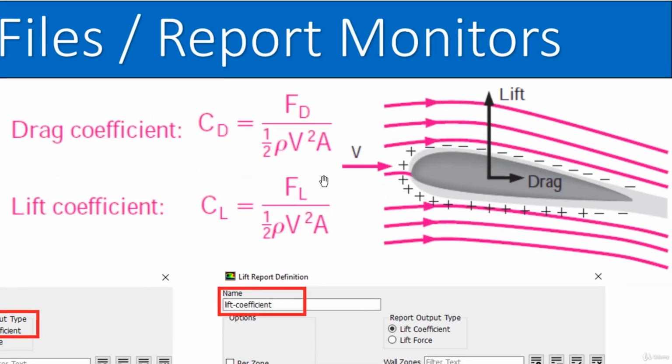To define the x and y components for the drag and for the lift, I want to show you how you can understand which component should go where. Flow is coming at a zero angle of attack, that is, the angle between the chord line and the flow is zero. But in this case, the flow is coming at an angle of 10 degrees from the chord. So it means that the drag coefficient will be in the direction of the air, which is here.